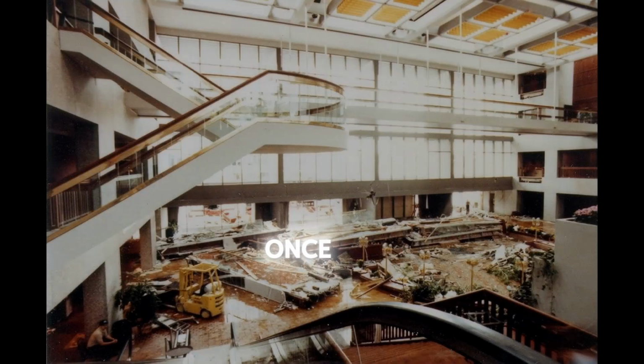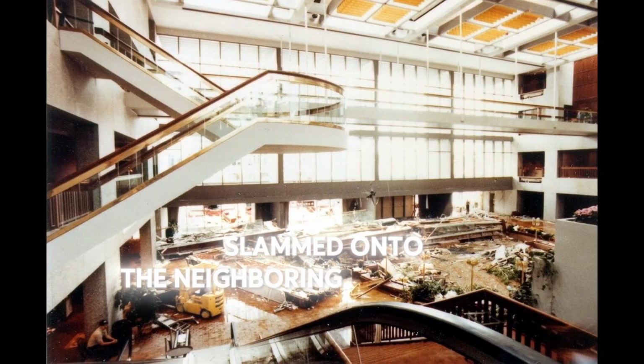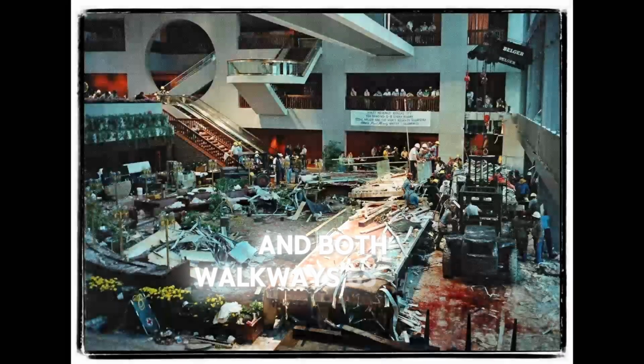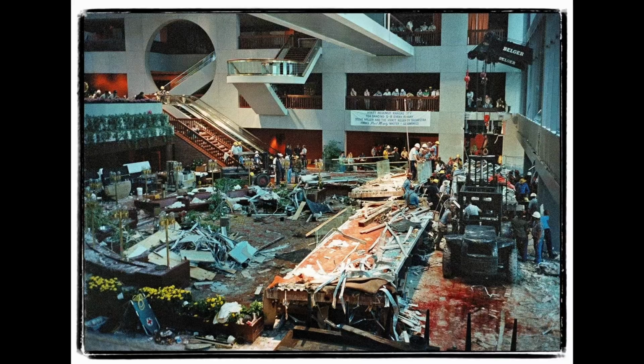As the load increased, the steel around the washer began to deform and the washer started to pull through the beam, tearing it open along the weld line. Once one connection let go, its share of the load slammed onto the neighboring connections. As a shock, they failed almost instantly, and both walkways, 65 tons of steel and concrete, fell into the crowd.